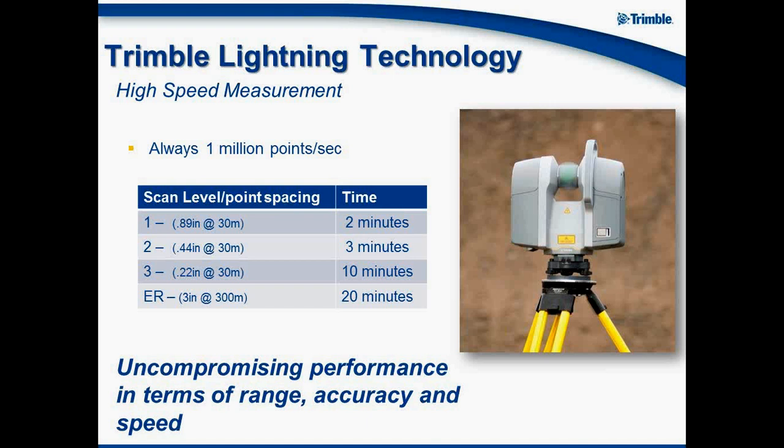With that 4-pass, you're going to see an increase in time, which isn't quite equal to 3 times 4 if you're doing the level 2. It's going to be less than that, but you'll also want to frame in an area specific, so you're not going to do a full 360 scan with a 4-pass. We'll frame in an area smaller, say a building or a bridge or something like that, so you don't spend as much time over scanning, so you can move on quicker.